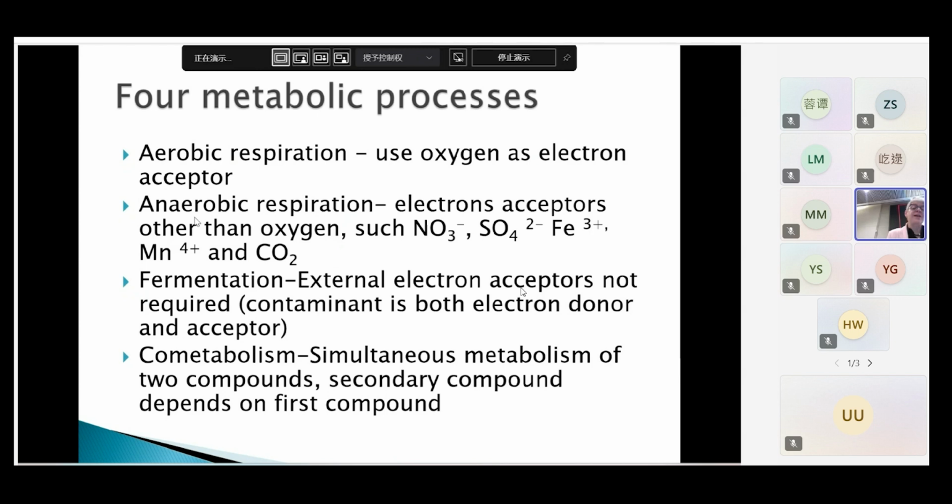If the non-engineered natural attenuation doesn't work, you could add some engineering procedures, such as adding oxygen to the soil in different ways. You can add oxygen by adding aerated water. You could use pure oxygen. You can add ozone. You could add peroxide, because when you add peroxide to water, it breaks down and then you get oxygen in this way. So there are different ways that you can add oxygen to the groundwater.